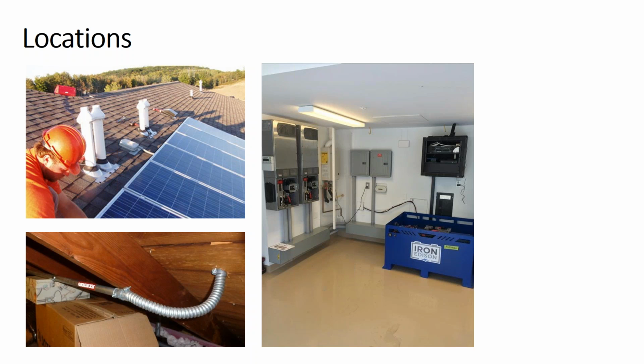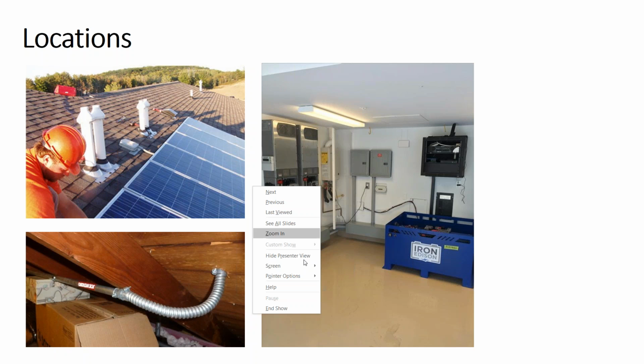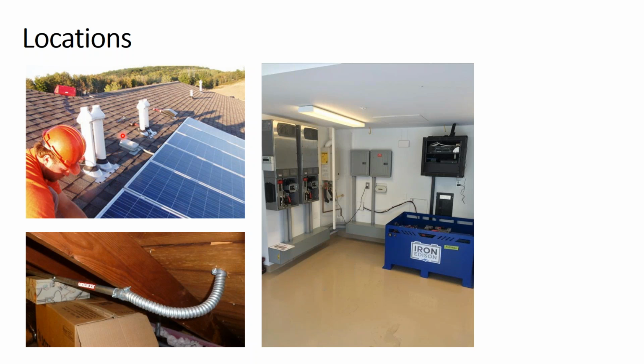And you might actually get onto the job site and maybe the wires up to this junction box are not installed yet. So here's our junction box. And you might have an electrician coming all the way up and landing on this junction box. That would be your conduit going from a dry location into a wet location. Those wires may not be there, and your solar installer may not want to energize and wire up the array on the module to box connection, because he knows there's an electrician with no solar experience doing this part, and he doesn't want to energize this box with his DC system until the electrician is out of there.